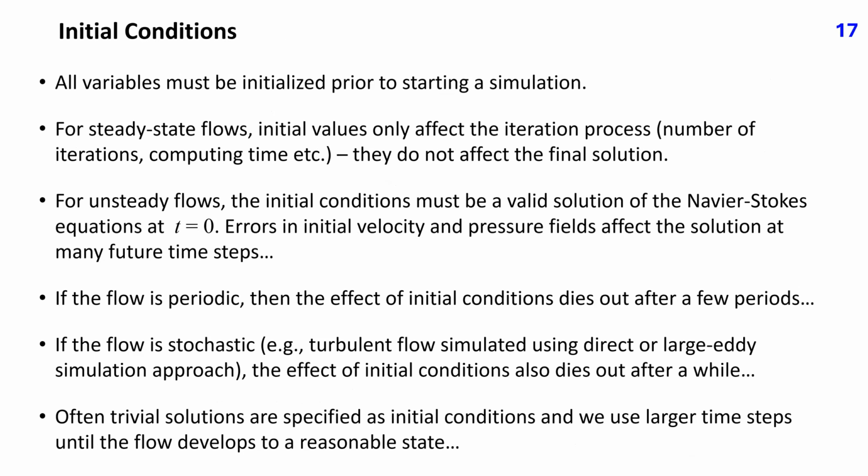All variables must be initialized prior to starting a simulation. For steady-state flows, initial values only affect the iteration process, that is, the number of iterations, computing time, etc. They do not affect the final solution. For unsteady flows, the initial solution must be a valid solution of the Navier-Stokes equations at time t equals 0. Errors in initial velocity and pressure fields affect the solution at many future time steps.